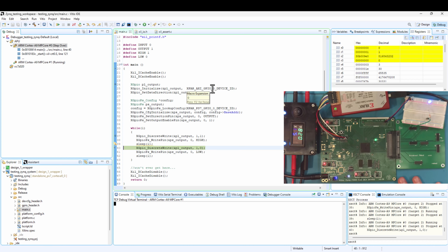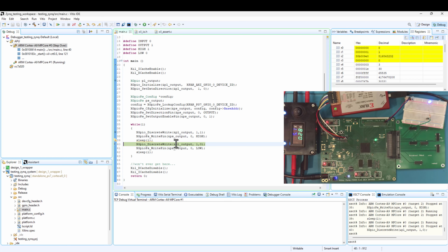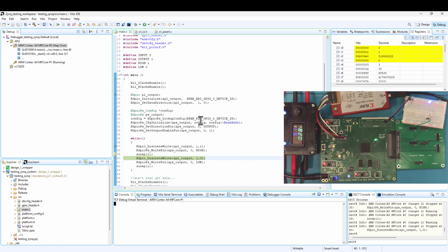So I'm feeling pretty good with that. I'll get the faster clock in later this week and just test what I have so far. Then I will come in and probably do the DDR testing next. And then after that, again, connect up this. And I will post an update as I make my way into that part of this assembly. But right now, I'm pretty stoked that this is all working. Debugging as I'd expect it to. Really, I'm getting the results I would expect to see at this point. And then I'll work on testing the DDR at the current speeds, and then I'll start bumping up the speeds and see if that had something to do with it or if there's something else going on.